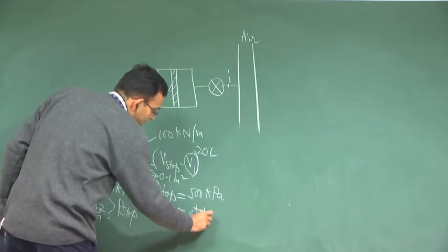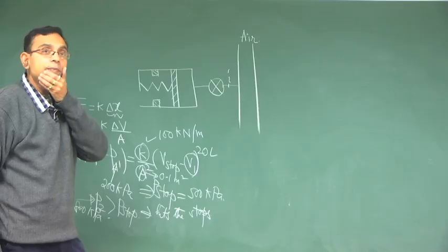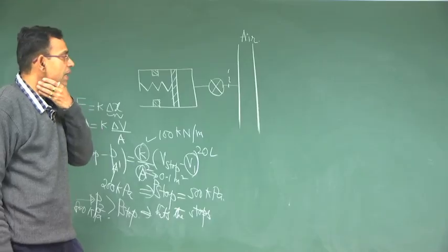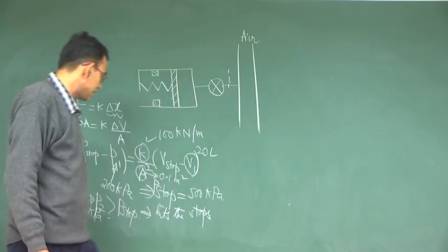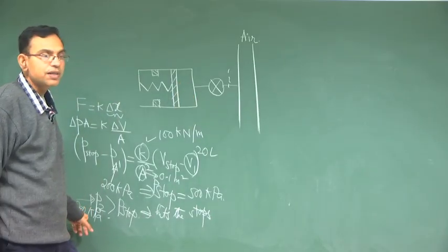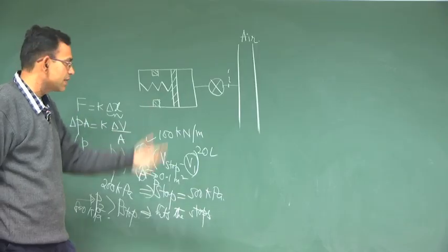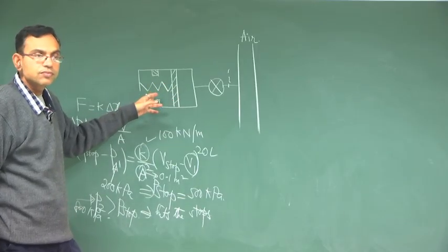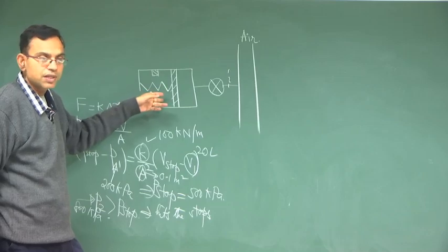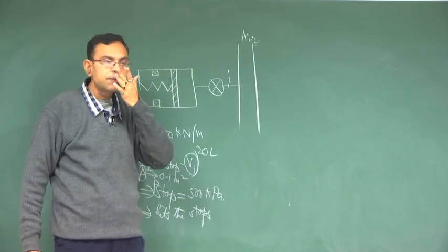See why thermodynamics problems are so interesting. I may plan for setting up exactly this same problem in your exam, but I change the final pressure from 800 kilopascal to 400 kilopascal. Then the entire solution changes, because then the piston no more hits the stops, it comes before the stops and the solution is different, although conceptually it is a similar problem.